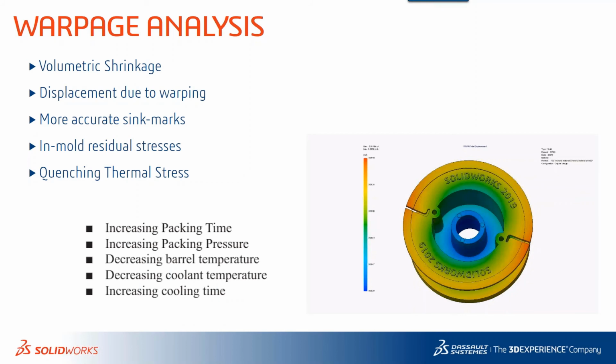That's 4 steps. So we can essentially recreate that realistic process right within SOLIDWORKS Plastics. The third step is running that warpage analysis. And typically you want to run a warpage analysis in your second or third iteration without any cooling line first, because you want to see how your part may displace without any type of cooling and only taking into account natural convection. So no forced convection at this point included within the analysis. So this will give you your maximum displacement if there's no cooling lines.